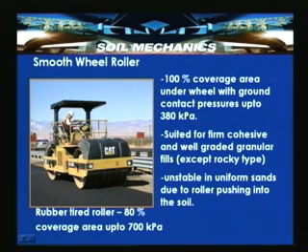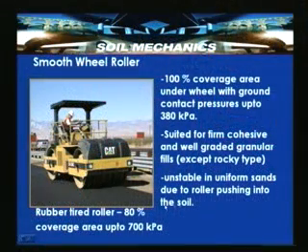Except for the rocky types, well graded granular fills can be compacted, but this multi-tired roller, or a smooth wheel roller, cannot compact uniformly graded sands because of the roller pushing into the soil. It is unstable in uniform sands due to the roller pushing into the soil. So, 100% coverage area under wheel load with ground pressures up to 380 kilopascals is suited for firm cohesive and well graded granular fills, except rocky type soils.